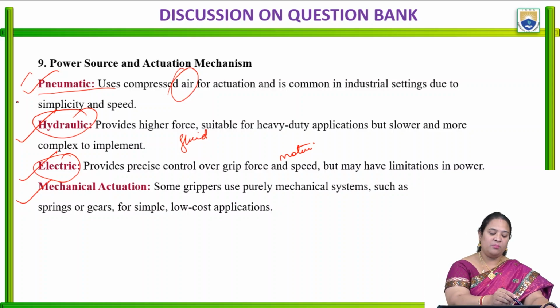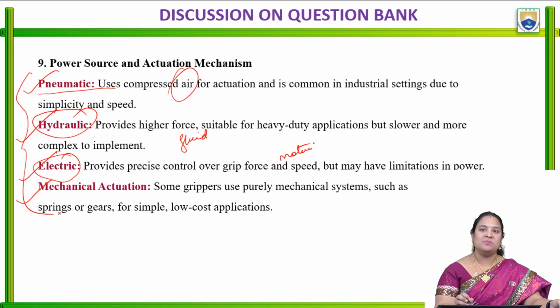So these are very important concepts. When air is sucked inside and releases a high amount of pressure, it moves the cylinder head in the forward direction, resulting in the movement of the end effector. In the same way, when fluid is sucked inside the piston, some amount of pressure is generated, with the help of which the cylinder head is moved and the robot's end effector starts moving, right?